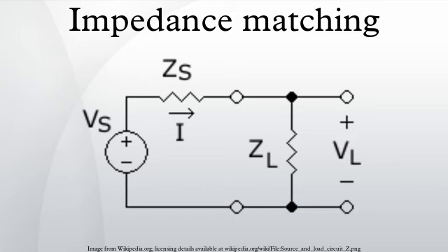For two impedances to be complex conjugates their resistances must be equal, and their reactances must be equal in magnitude but of opposite signs. In low-frequency or DC systems the reactances are zero, or small enough to be ignored. In this case, maximum power transfer occurs when the resistance of the load is equal to the resistance of the source.